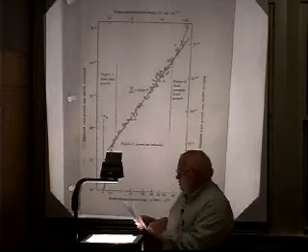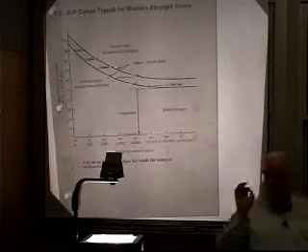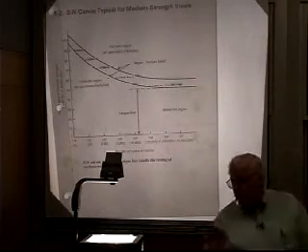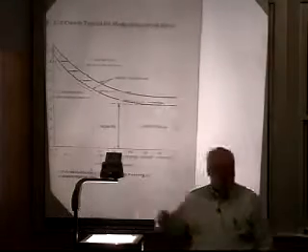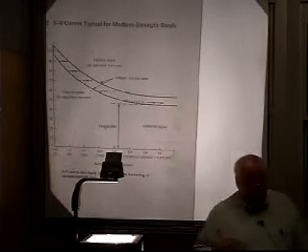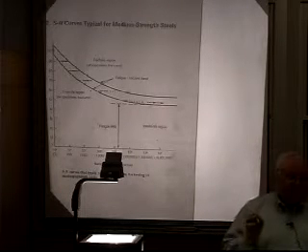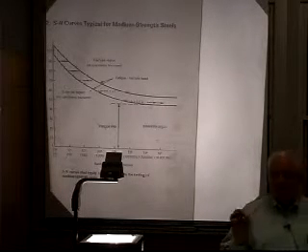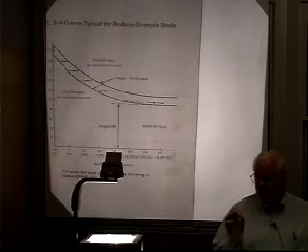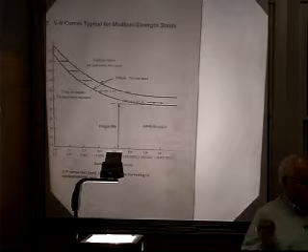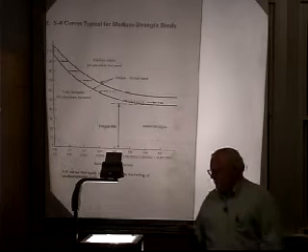Well, it turns out what really controlled this fatigue limit? The small flaws, the small imperfections that were in the material originally. You might have a flaw in a typical steel. If you just go take some garden variety steel off the shelf, you'll have flaws that are around 4 to 10 thousandths in size as a maximum flaw size. Those are just the inclusions in the steel. 4 thousandths is about 1.5 human hairs. 10 thousandths is about 4 human hairs in size.